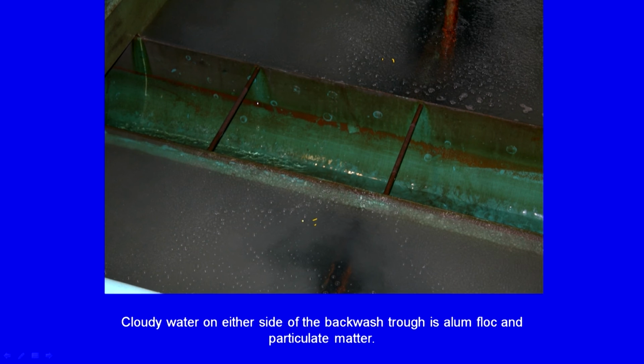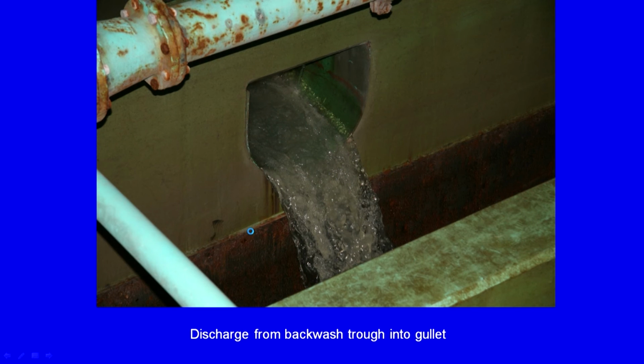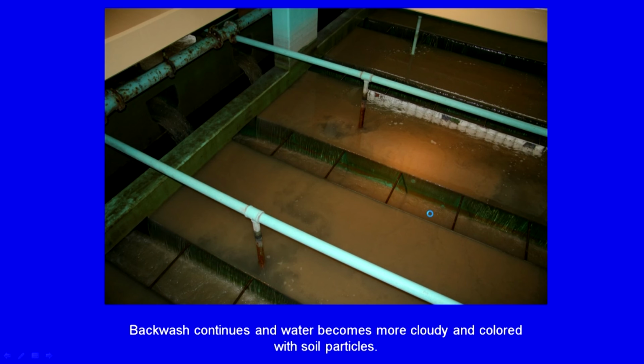Why is this? This is alum floc and particulate matter. Looks like before this they had coagulant being added, which was alum. So, when they are backwashing, you see that this cloudy material is alum floc and some particulate matter on the surface. And obviously, from the backwash trough, it is being collected in the gullet. And now, after backwashing is continued, more of the particles that are adsorbed are going to be desorbed, if I may say so, and they are going to come out here.